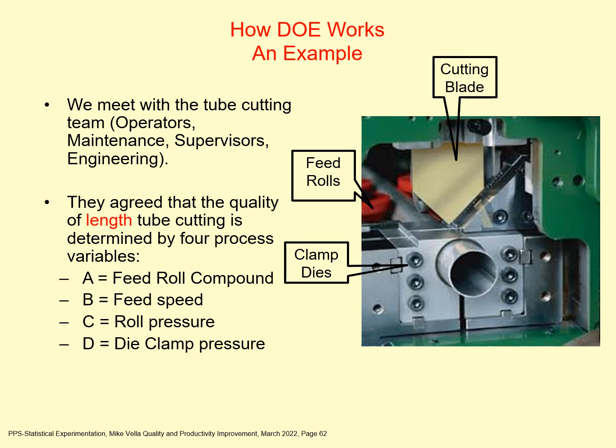So you can see on the right-hand side a cutting machine. The tubing that you see being pushed through a set of clamp dies is fed by pushing or rolling feed rolls. Those are the orange items sort of in the background. As the tubing comes through the dies, the tubing hits a feed stop and the dies close, clamp onto the tube, and the cutting blade comes through horizontally, slicing the tube to length, and then the process starts again.